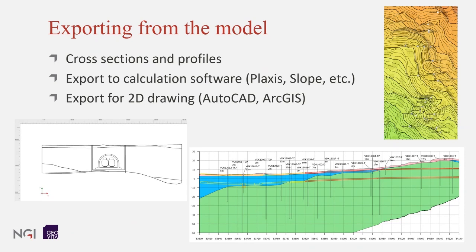We created a Plaxis 2D model with interfaces and materials and so on. And then you just copied the calculation, removed the layering, and imported new layering from another cross-section. Since the cross-sections are based on the railway alignment, they are all centered correctly, so you don't have to move anything or decide the position of the center of the building pit. You can have the new calculation up and running in a very short time frame.